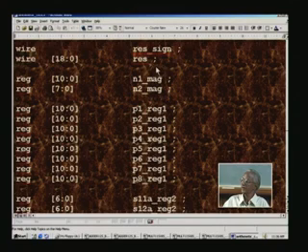For the final result, the sign is also required, and we have to keep track of it, because we are evaluating the magnitude using the algorithm. The magnitudes of the two numbers n1 and n2 are declared as registers, which we will be evaluating. We also declare other registers which happen to be in the always block, and they are all at different clocks.